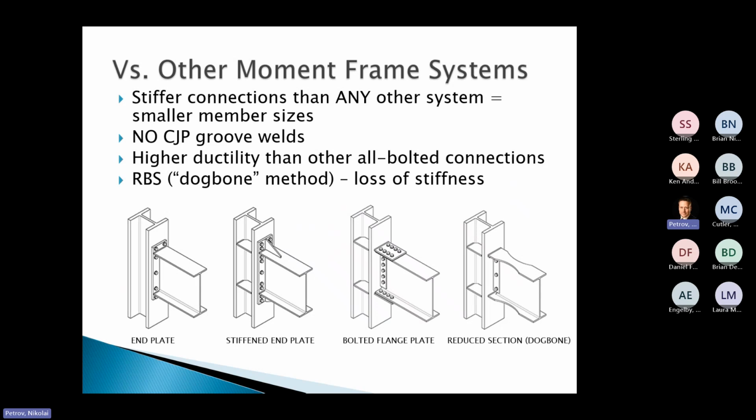And some of the design software that we use, Bentley RAM Structural System, we use to design buildings quite a bit. And they have a plugin for SidePlate that allows you to put some additional information in, and then it will actually do that process where it uses a shorter beam length, I think a shorter column height, in calculating moment frame stiffness, so that you can capture some of that economy and end up with some smaller sizing to get your building within the deflection limits.